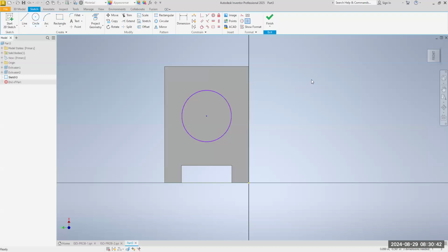When you finish the sketch, you have to do a right click to okay. All right, now, I like where the circle is at for the most part. If I click on this dimension here, dimension tool, and dimension those 2 points, I'm happy with that dimension. That's in the middle. I know it's in the middle because I snapped to the midpoint earlier. So I know that dimension is correct. But what if I want to dimension this one?